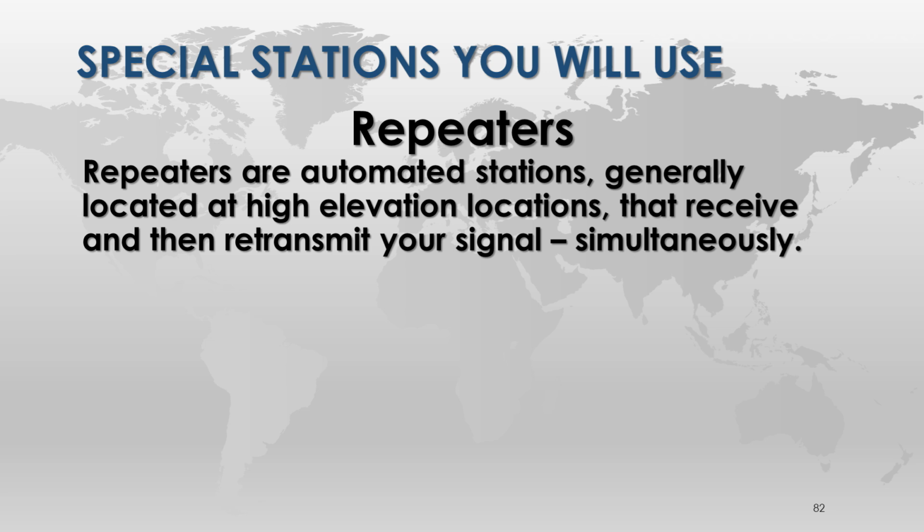So do I need to program the upshift? Yes. Many modern radios will automatically put in the positive and the 600 kilohertz. But you've got to tell it it's a repeater to do that. So you need to know both numbers then, right? Nope. You only need to know the standard is 600 kilohertz for 2 meters. It's 5 megahertz for 440. As long as it's a standard offset, you need to know the one frequency, the one you listen on.